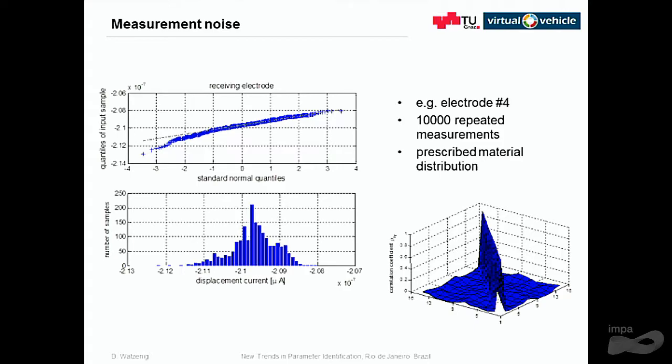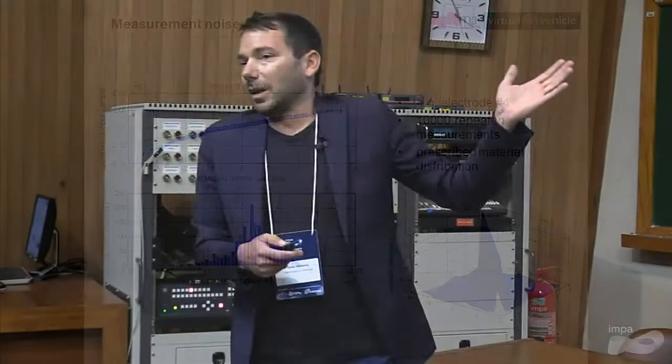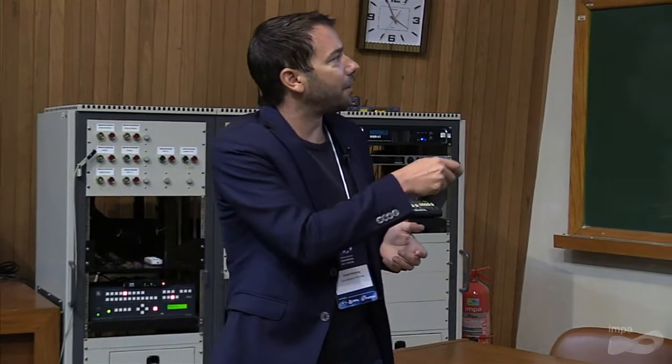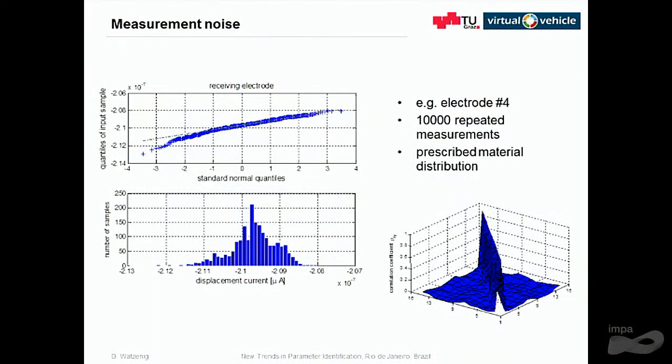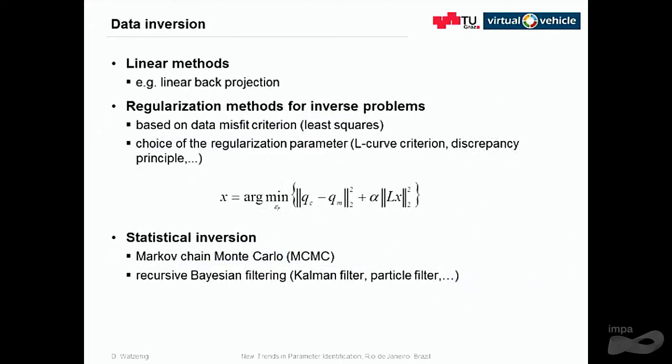In that case, we see that in that region, we are quite good, well distributed in the Gaussian white noise. But to the tails, we are losing this Gaussian distribution, so we have to work out if we should consider that or not for our reconstruction process. In fact, the explanation why we have this kind of setup is that there is a certain crosstalk between the electrodes, and we have a certain deviation from this optimal white Gaussian noise. That's the correlation coefficient also worked out from the measurements.